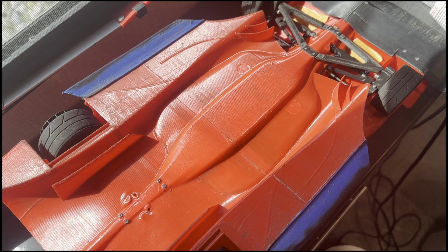But this being an RC car, I need orders of magnitude more ground clearance than a full-size car needs. So the flexible edge seal allows me to run the car basically touching the ground at speed. The shape of these edge seals helps to kick up the air as it comes over the top of the floor edge, and I have two separate vortex generating tube structures.